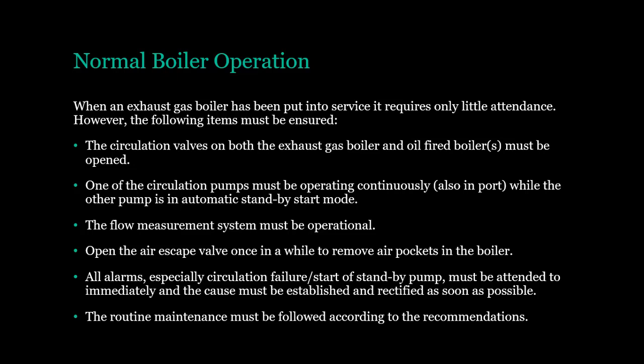Open the air escape valve once in a while to remove air pockets in the boiler. All alarms, especially circulation failure/start of standby pump, must be attended to immediately, and the cause must be established and rectified as soon as possible. The routine maintenance must be followed according to the recommendations.